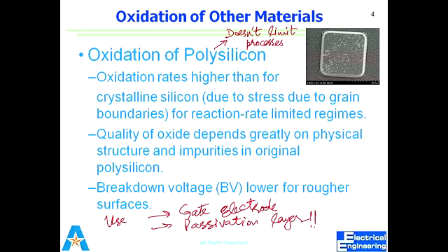I'm not concerned with the quality of the oxide. Even in the case of a sacrificial layer of oxide, I would like to have an oxide layer that is easy to etch away. It should not be that crystalline. So I don't need a better quality because I need to remove it later on. That's why it depends upon our application what type of oxide layer we need.